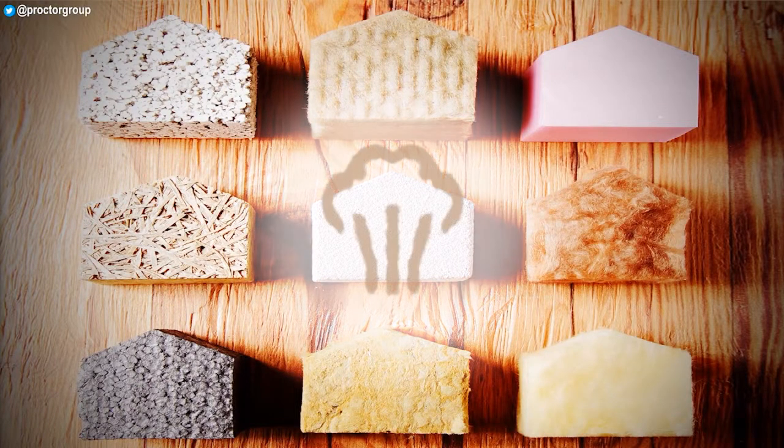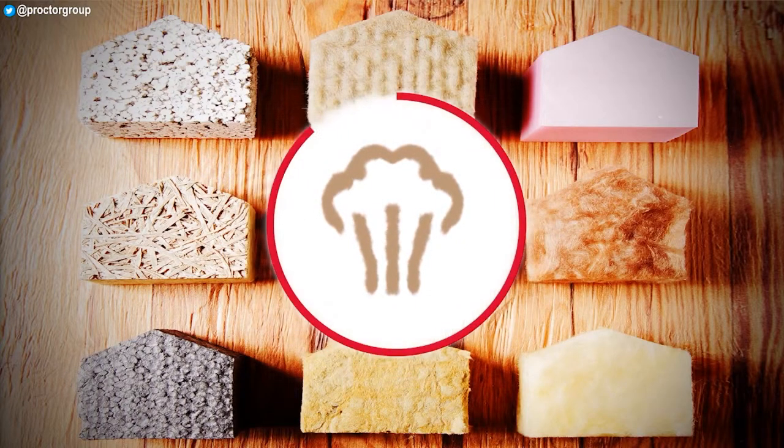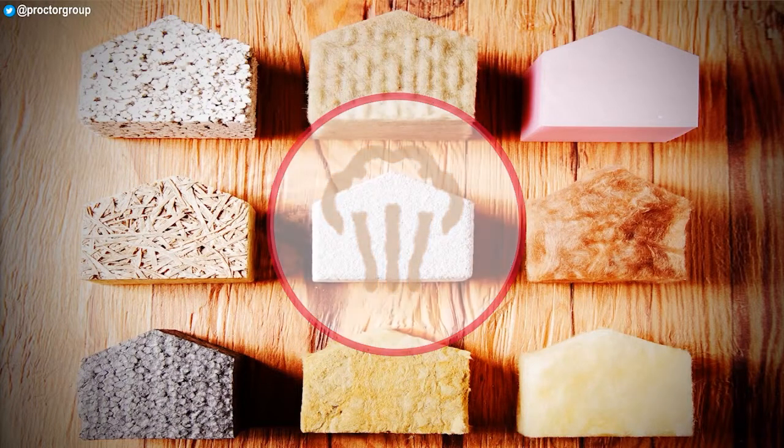The first of these challenges is that older buildings typically benefit from highly vapour permeable insulation. This is because traditional building materials such as lime-based mortar and plaster have very different hygrothermal properties from their modern equivalents. Adding insulation of low permeability, such as rigid foam, on top of such materials can lead to damaging moisture problems for two primary reasons.